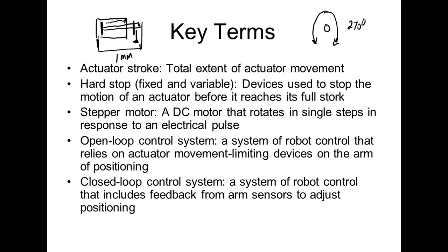You understand that as far as where, and this is real true on electric actuators, they don't like to be stalled. Getting something in motion takes a bunch of power. So when you got an electrical actuator at a standstill, when you start it up, it pulls a lot of electrical current. We call it start current.